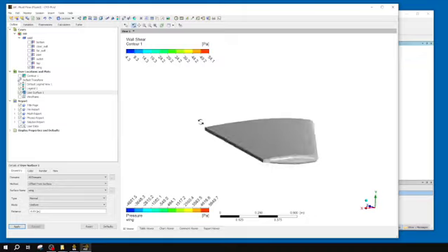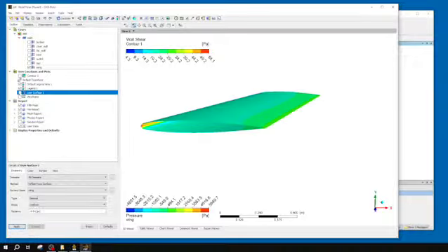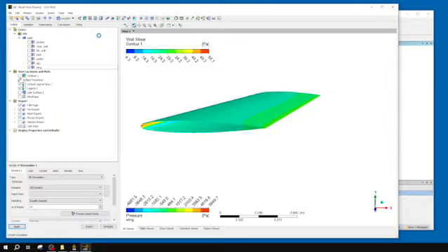While I do love these offset surfaces, I love them because I can hide them and use them for other things. So I just unchecked that box real quick, and I'm going to move over to my streamlines now and make some custom streamlines. So if I press OK, I can start my streamlines now from that defined surface. If I start them on the actual surface of my material, since we have a no slip condition, our velocity on the surface is 0, and that is no good for streamlines. They have nowhere to go, so that's why we need this little offset surface.